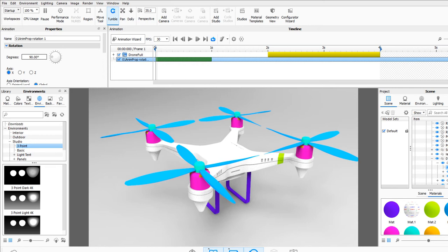A drone has to spin around like a bajillion times in order for that propeller to spin enough to get it off the ground. So I would typically put in 9,000, that's probably about an accurate number. I probably would even go higher than that, maybe to like 12,000, and that is a sufficient number. You can verify it by hitting play and seeing.